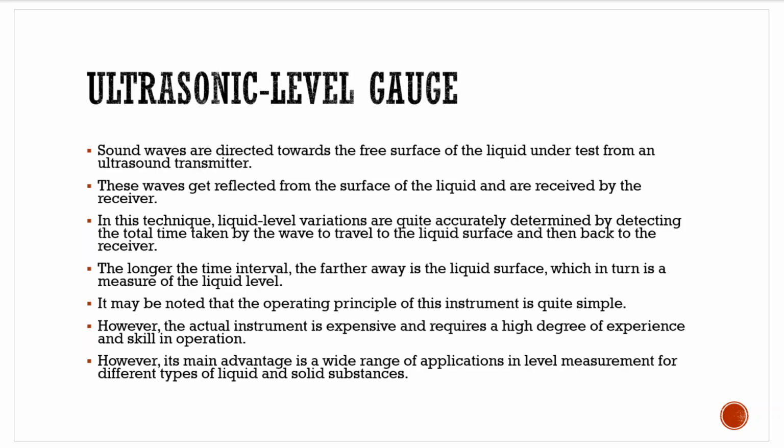Fine. So this particular method, although it's applicable, is quite expensive. You can understand that for simple measurement of liquid levels we are using ultrasonic waves. We have to generate them, then transmit them, and then receive them. So the actual instrumentation is expensive and requires a high degree of experience and skill in operation. But the advantage is that level measurement for different types of liquids and solid substances is possible using ultrasonic level gauges. Fine.